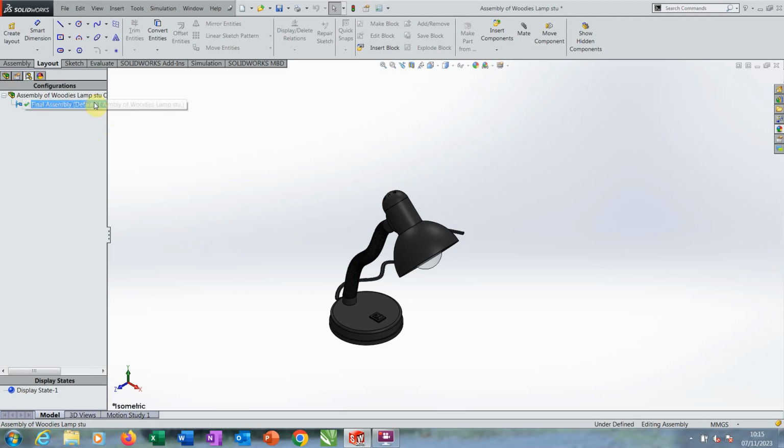Right, so we need to create another file here, and you must have this opened, or you must have it highlighted. Then we press Control C, let go, and then press Control and V. Okay, and that will give us a copy up here. So the first thing we're going to do is the exploded view. So we're going to rename that. Do the very same, click on it twice there, and we'll go exploded view.